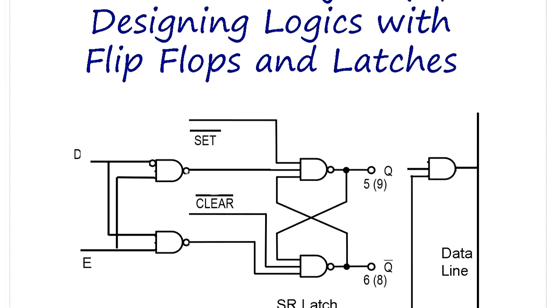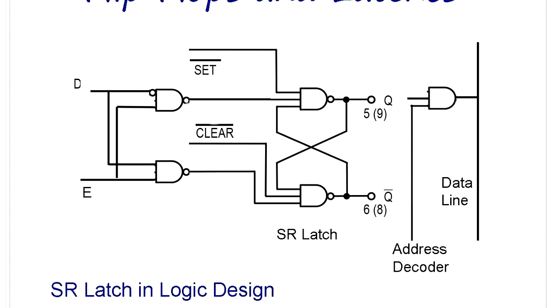So this is a typical SR latch or RS latch, whichever you call, and actually this is a section of the latch. So what happened is the latch, you have a set. If it's active low, when it's low, it's forced to the Q to be high, and this is high, and there's no clear, then this goes low. So you set output high, that's a set, and clear is the opposite. You set Q bar high and Q will be low.